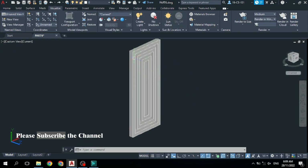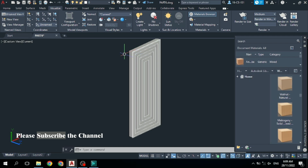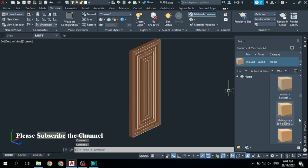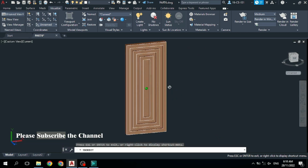If you want to add the material, you can add. Simply come to visualize and click on this material browser, and here different materials are available. You know that. So simply click on this wood. You can see down this wood, so simply click on it and now you can add the materials. Select this door and now let's add this material. You can add, all materials are available. After that, close this. Now you can see your door is completed, and now copy it and sit